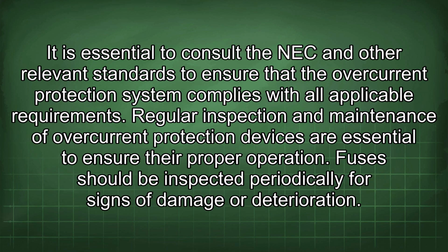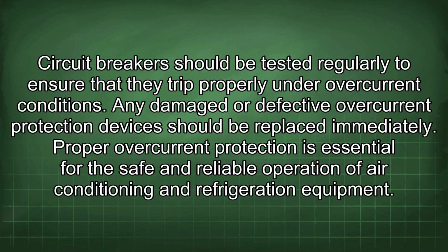It is essential to consult the NEC and other relevant standards to ensure that the overcurrent protection system complies with all applicable requirements. Regular inspection and maintenance of overcurrent protection devices are essential to ensure their proper operation. Fuses should be inspected periodically for signs of damage or deterioration. Circuit breakers should be tested regularly to ensure that they trip properly under overcurrent conditions. Any damaged or defective overcurrent protection devices should be replaced immediately.